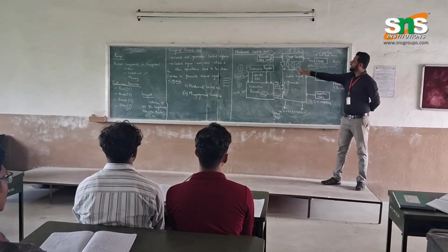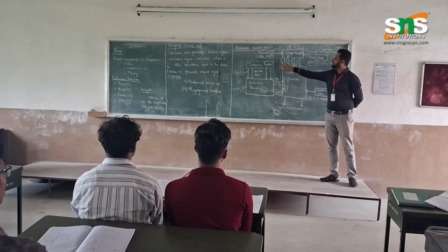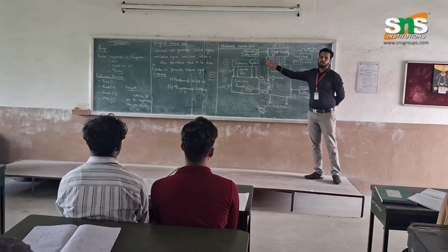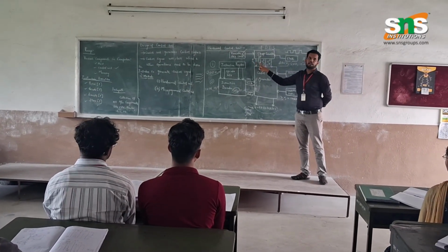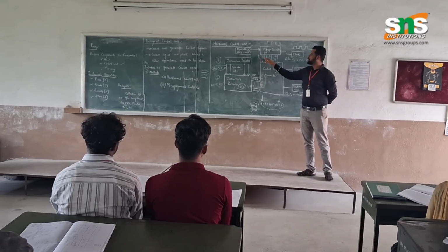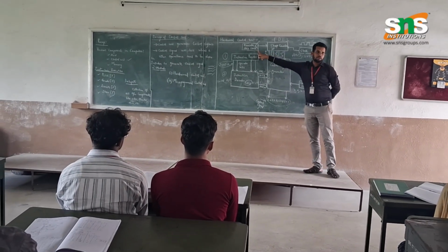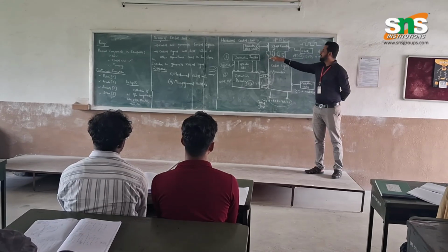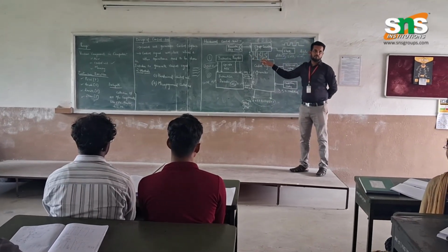But every time an instruction is executed, it takes different times. The fetch will take a different time, the decode will take a different time. So in order to handle that, we use this enable step counter to decide at what time the decode will be done, and at what time the execute will be done.